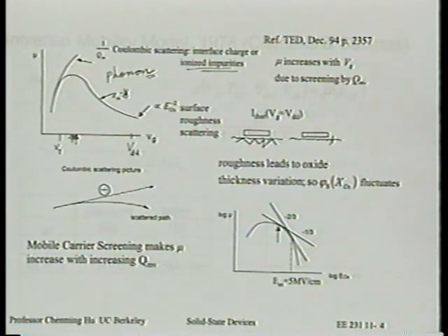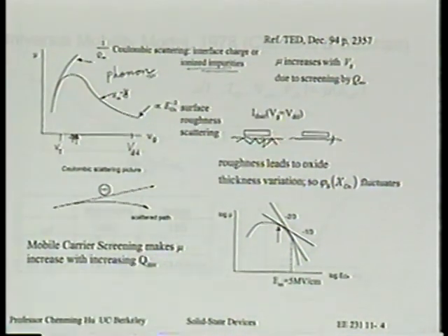That's a very important fact because that really made the modeling possible. If not, you cannot predict what behavior a transistor will have until you make it and figure out what the mobility is. Fortunately, we don't have to. Mobility is very predictable, it turns out. That's not responsible for any lack of knowledge of the transistor behavior. It's not mobility today. Yes?